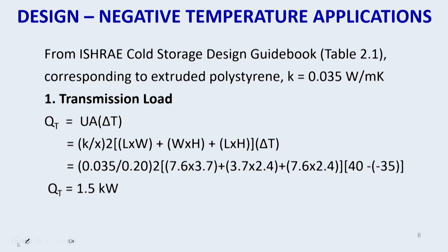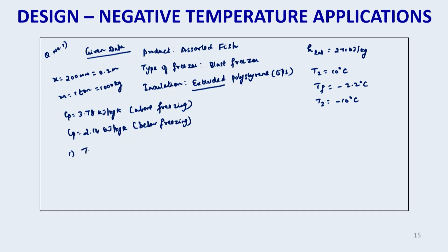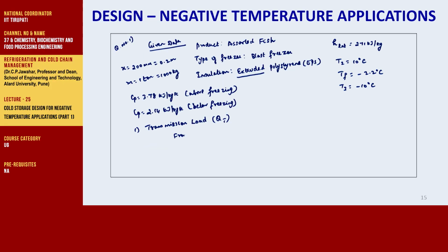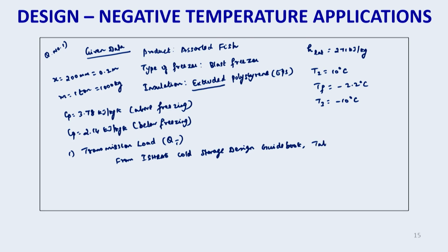So let us calculate the transmission load. First one is transmission load, QT, from the ISHRAE cold storage design guidebook, table 2.1.